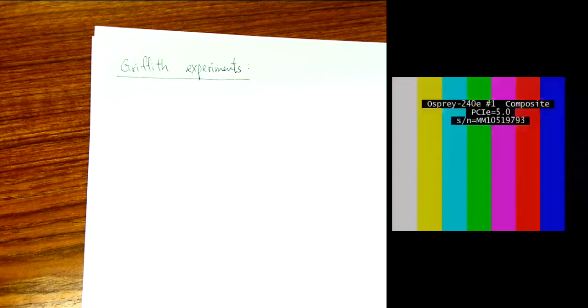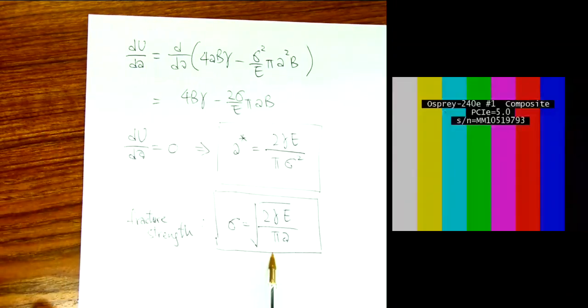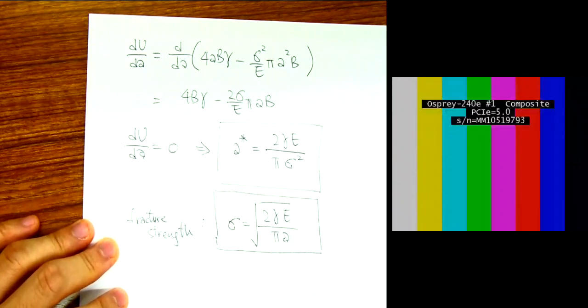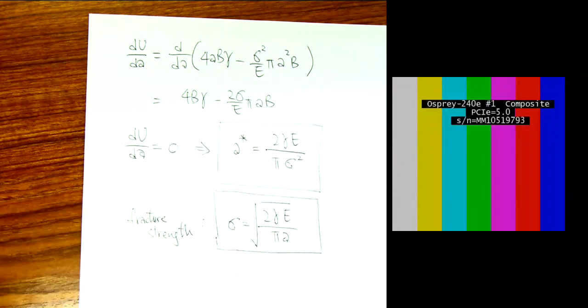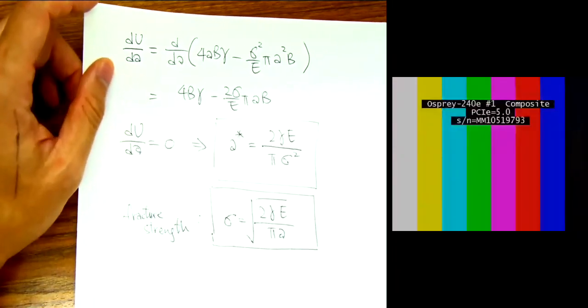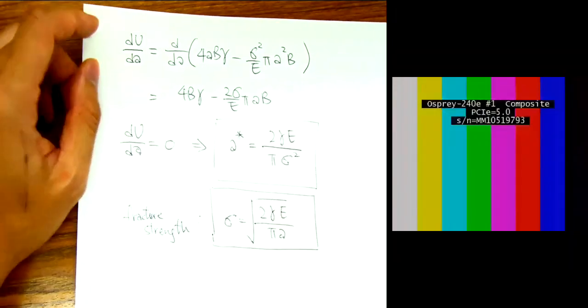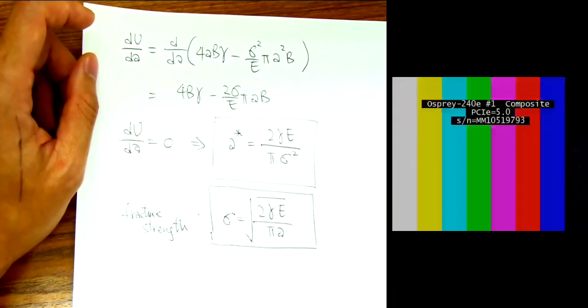So what we need to prove, we need to be very clear about what we want to prove, right? This is the equation that he derived. And think about this. There are two variables that can be changing, right? That is sigma and A. I take a piece of material, the loading can be changed. I can change it by loading it more and less. There's the crack size. That is something I can control. Okay, I'll tell you how he controlled it. What is not going to change is elastic modulus and surface energy of the material, right? You give me the piece of material, I cannot change these two things.